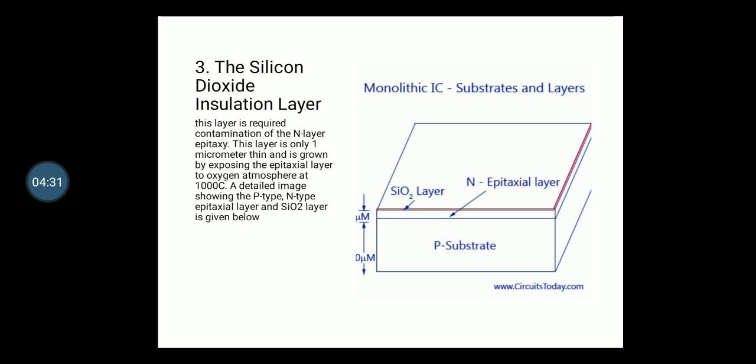Now the silicon dioxide insulation layer. This layer protects the n-layer epitaxy from contamination. This layer is only 1 micrometer thin and is grown by exposing the epitaxial layer to an oxygen atmosphere at 1000 degrees Celsius. A detailed image showing the p-type, n-type epitaxial layer and SiO2 layer is given in the image.